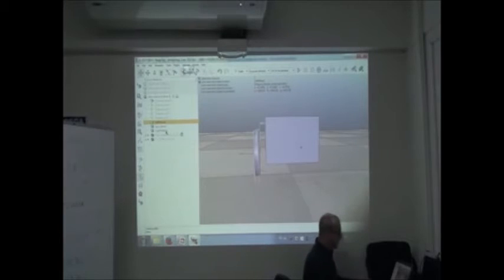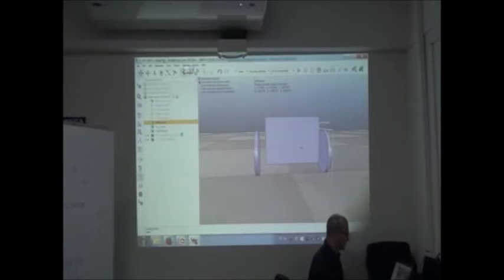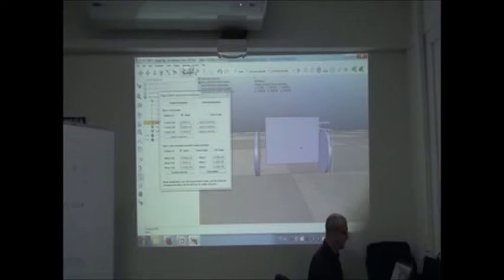Now let's move this left wheel that we selected into this place here. We have 0, 0 here. So I press this button, and I see that the position is 0.1, 0, and 0.05. But I want the wheel to be here. So basically what I need to do is modify the position to the other side of the frame by putting the minus here. Translation, put the minus here. And obviously you put that on the other side. Okay?